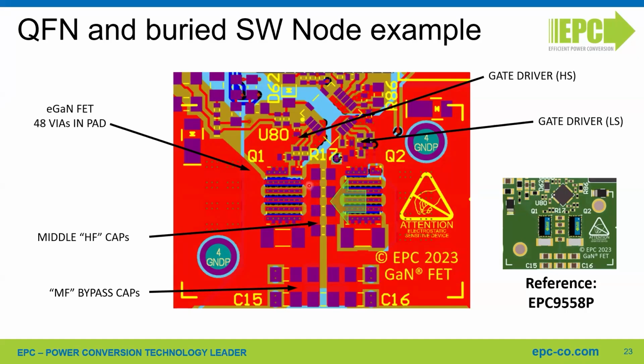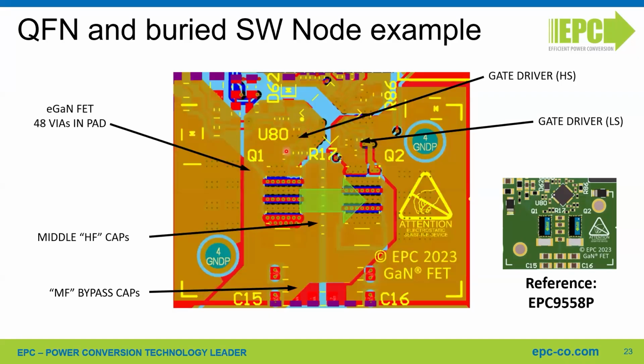and it can provide a really low amount of parasitic inductance. And regarding the gate drive, it's worth noting the high side gate drive circuit up here, including the bootstrap capacitor. So basically, this is the bootstrap diode. All of this circuit is laid out on the switching node, which is in the inner layer. And this is working as a return path for the gate drive currents.